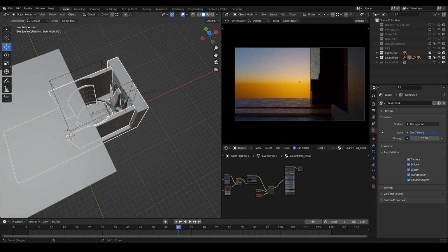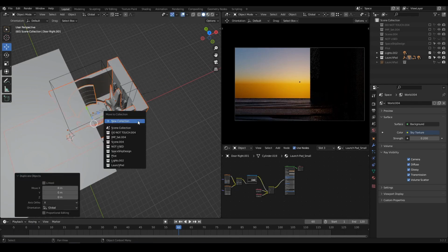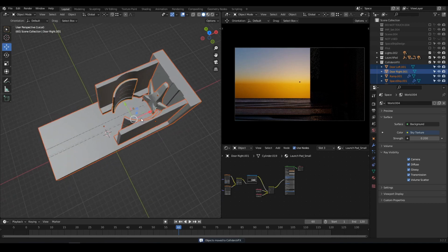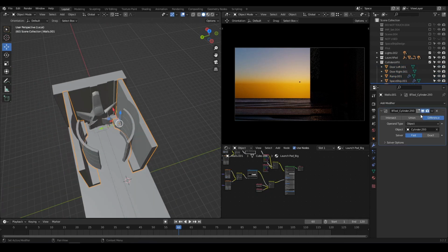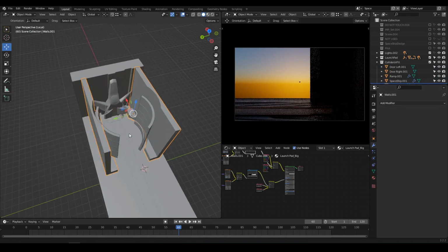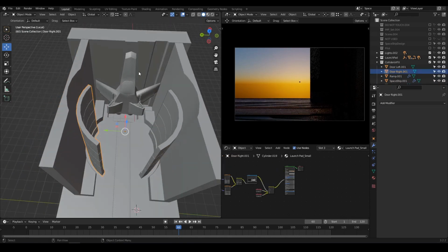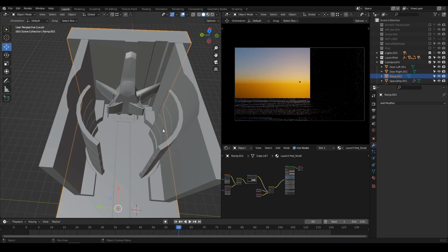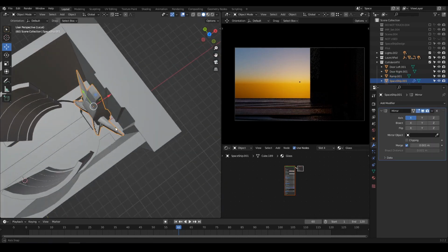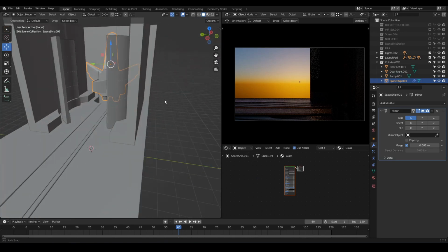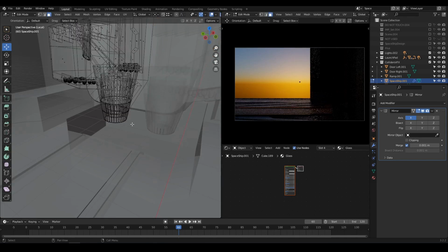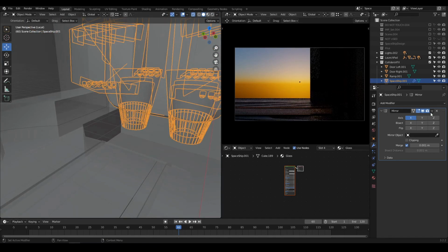Okay. I'm duplicating this object and placing them in their own collection. So then from now, I'm just gonna apply the modifiers that are already on this object and then add a modifier which is called remesh. Okay, this allows me to remesh the geometry from this object to usually a much lower resolution object, because as I'm gonna use them as a collider for my simulation, you want them to be as simple as you can, because otherwise the more complex they are, the longer the simulation will take.